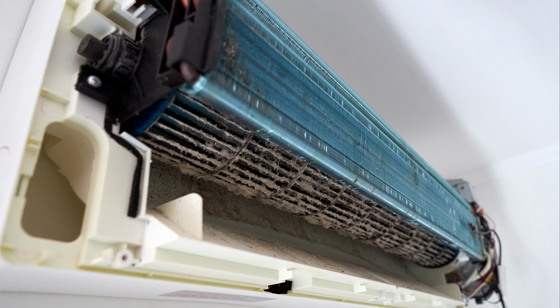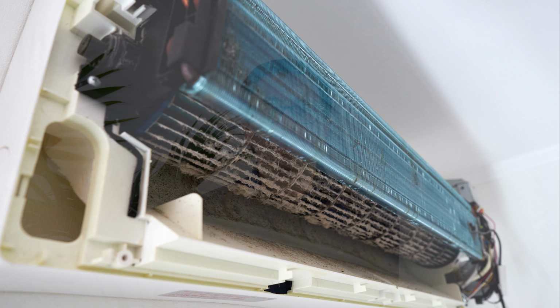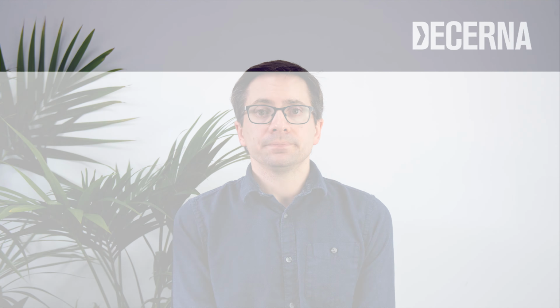Air-to-air heat pumps are generally very reliable, but as with other air conditioning systems, they do require some maintenance. As a minimum, an annual service should be carried out by a qualified heat pump engineer. They will ensure that things like the heat exchangers are clean and free of debris or weeds, and that the pipe lagging is all intact and in good condition. Also, they'll check that there are no refrigerant leaks and that the correct volume of refrigerant is still present in the system.